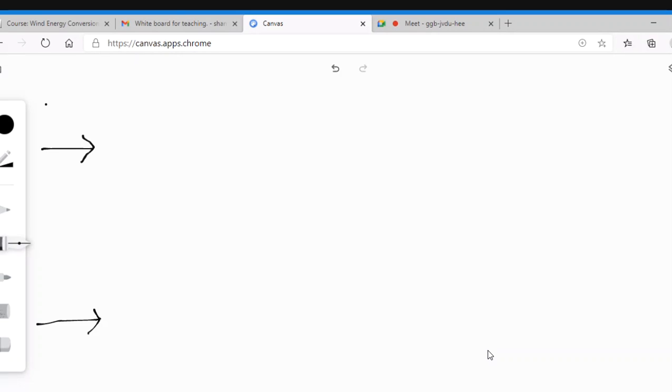IDS and IQS come from the ABC to DQ transformation of IAS, IBS, and ICS, the stator currents. Because stator is stationary, you can easily measure the stator current IABCS by using some Hall effect sensors. Okay, now ultimately, what are the variables in front of you? IDS and IQS you can easily get by using current sensors. Only these two variables are in your hand and you have to express the other things in terms of these two quantities.